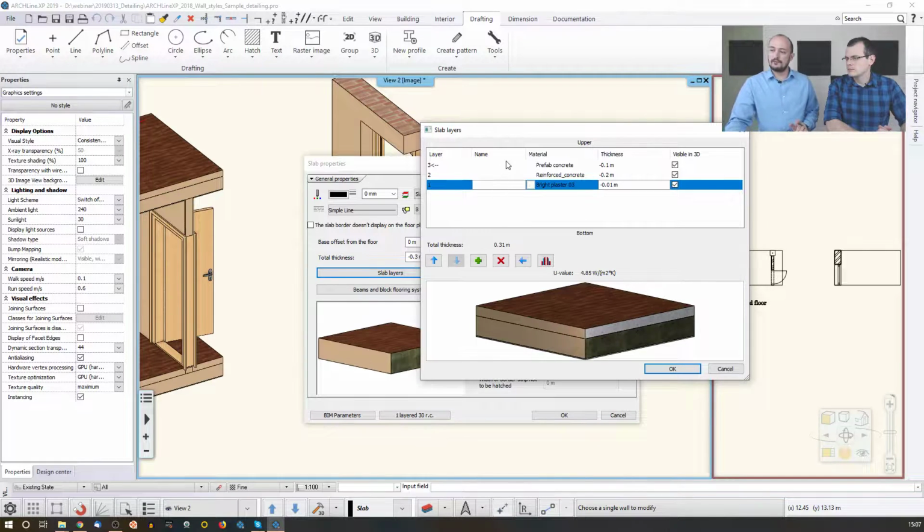There is also a name field here, and this is good because these are more descriptive than the material name. Now the material name is bright plaster or something like that, but I can type a real maker name, because this is what I will see at the end in the quantity takeoffs and the schedules and things like that. So I can add those details, but on the other hand, there is one last thing at the end of this row.